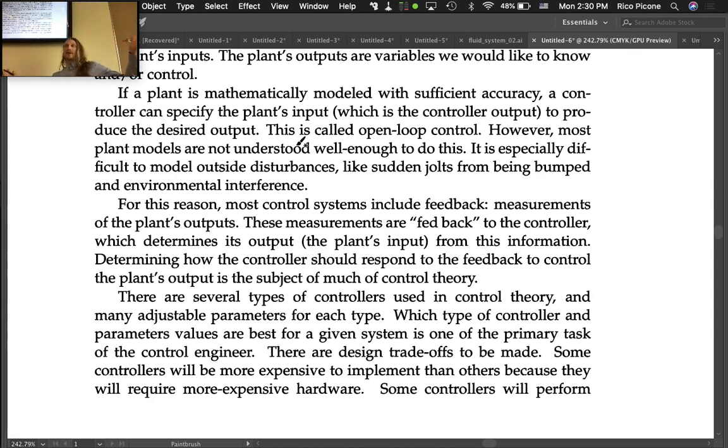There's an infinite number of possible values for these gains, and so you have a really large design space. Even if you just choose a PID type controller, you still have an infinite design space where you can choose three variables out of all the real numbers. Assuming you have that much ability in your actual physical controller, which usually there's some digitization, so you don't have that much, but you have a lot of options. Huge design space. So which type of controller? PID is the one we're going to focus on in this class, proportional integral derivative, and we're going to talk a lot about it.